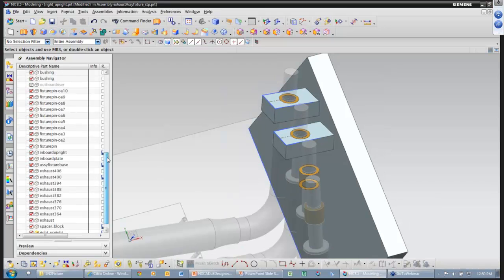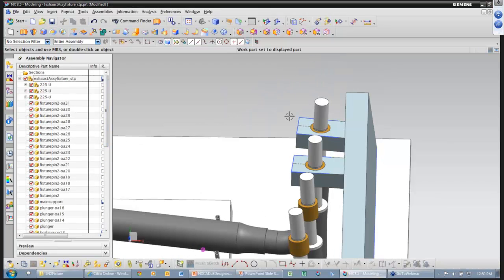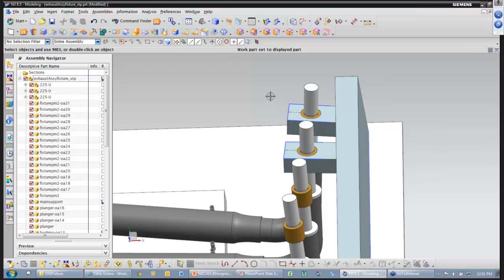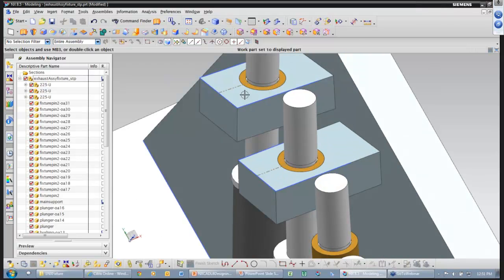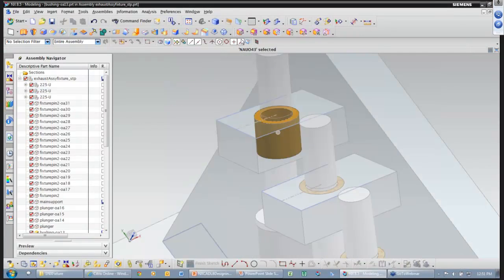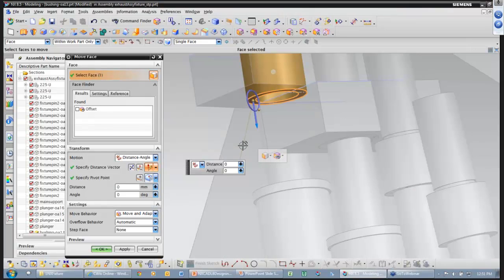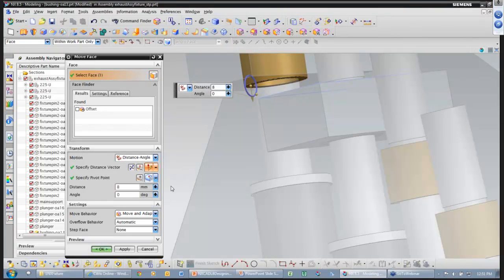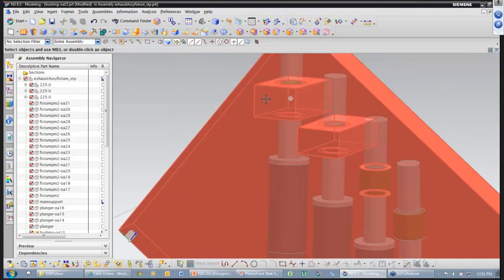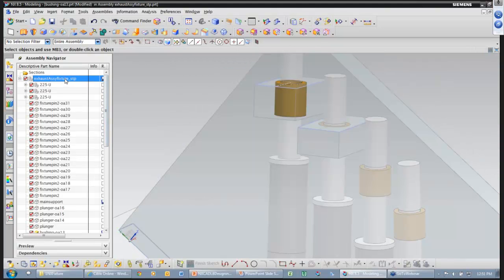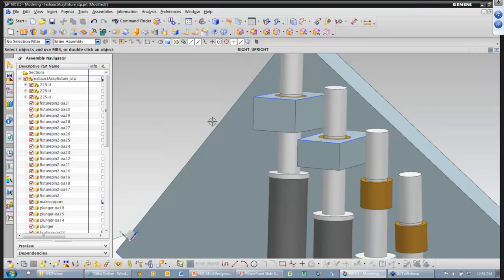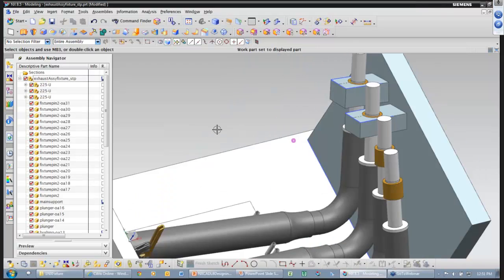So if I go back to my top level assembly, you see that not only did we model those in the context so we know exactly where they need to fit, but if I come in here now and change that bushing and make that a little longer, remember we extruded until that face, so you'll see that this thickness here actually got thicker too. If I go back to top level, this thickness, it went to that face. Updated associative.